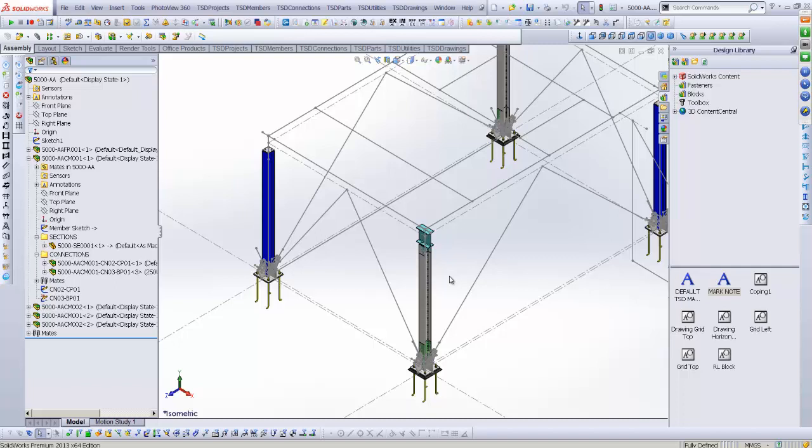You could, however, change your library drawing sheets as well to reflect this process, so that no matter what happens when you bring in your drawing sheet, it picks up that mark number as well. Now, I'm not going to go in and change my library because the library I've got here is set up for other reasons using default settings.